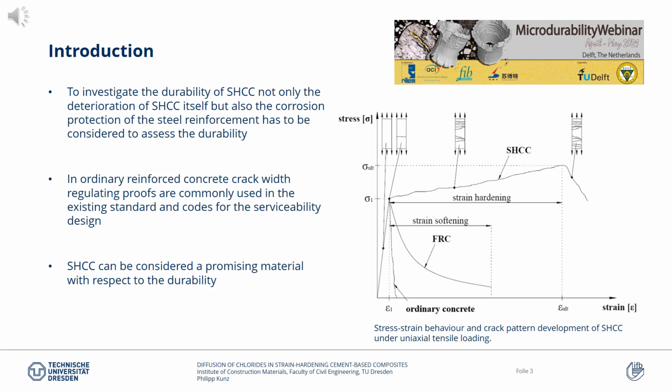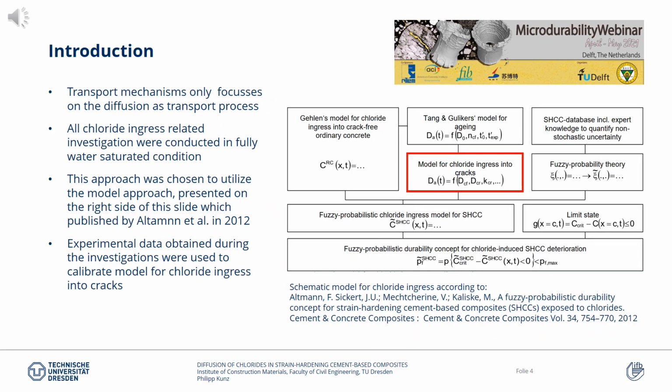Therefore, we conducted a series of experiments to enlarge the database for the durability related properties of SHCC. Within the framework of this paper, the description of the transport mechanisms only focuses on the diffusion itself as a transport process. Therefore, all chloride ingress related investigations were conducted in fully water saturated conditions.